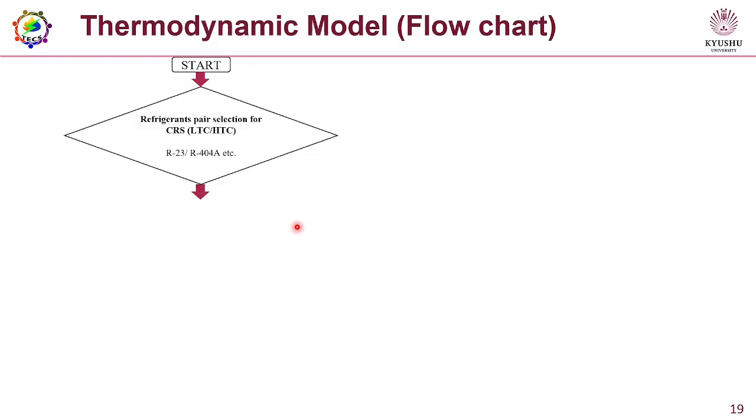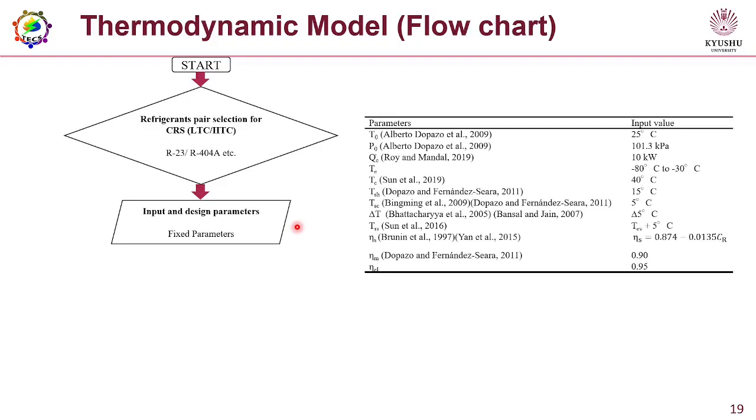The thermodynamic model starts with the selection of refrigerants after the input and design parameters like reference temperature, pressure, duty, condenser and evaporator temperature, superheating, subcooling, and compressor efficiencies.